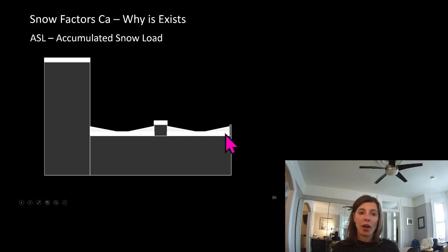I am doing a project in Huntsville right now, and the basic snow load on the roof is 2.7 kPa. The canopy, which has a high roof above it, ends up with 7.5 kPa of snow load on the canopy. That is an insanely massive amount of snow. And it, as you can imagine, very much governs the design of that canopy.